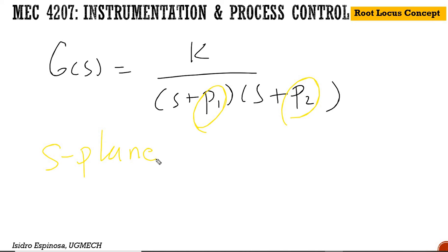Later, the root locus technique may be used with great advantage in conjunction with the Routh-Hurwitz criterion for stability and the Newton-Raphson method. So the root locus method provides graphical information for the engineer, and therefore an approximate sketch can be used to obtain qualitative information concerning the stability and performance of the system.